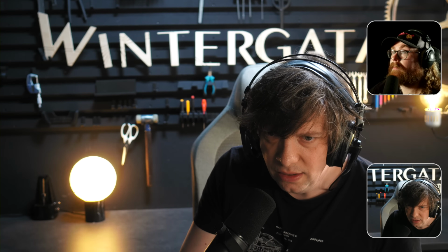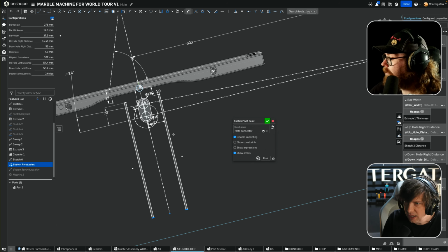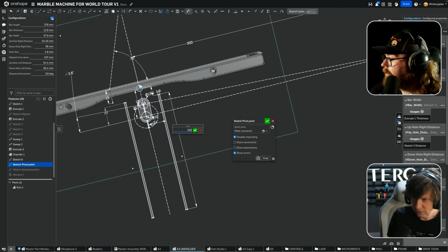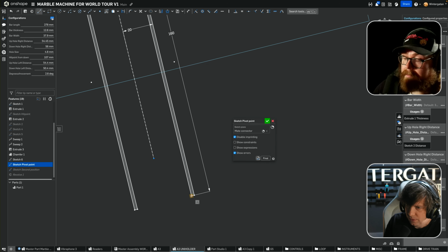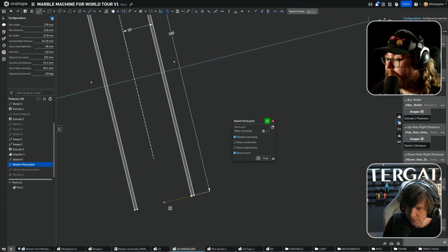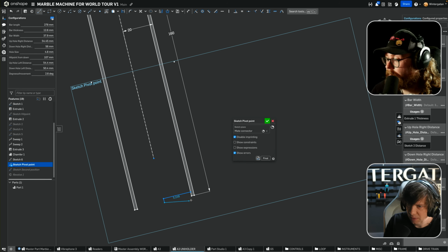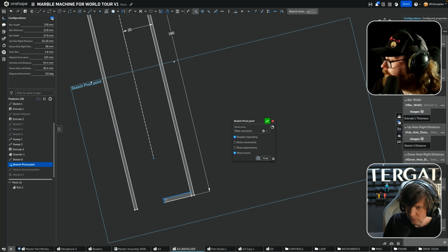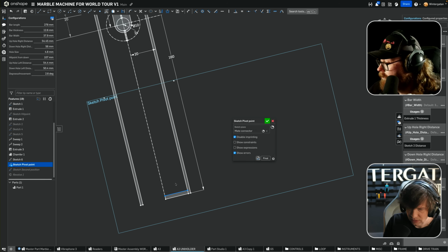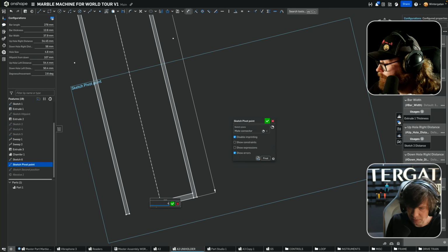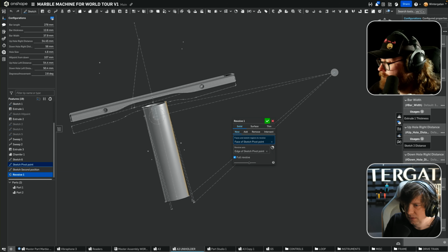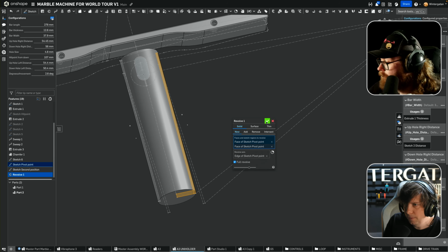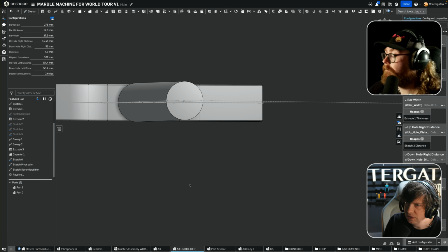So back in this sketch, we're going to add that value, 160. And we're actually going to make it closed off. So let's add a bottom cap here. These are coincident. And I guess the bottom is a little bit thicker. So now when I revolve this, the resonator is closed, as you can see.